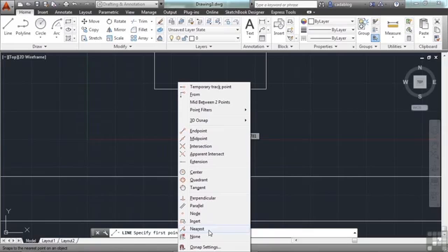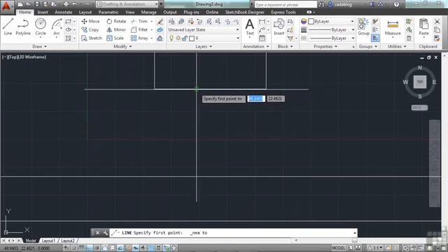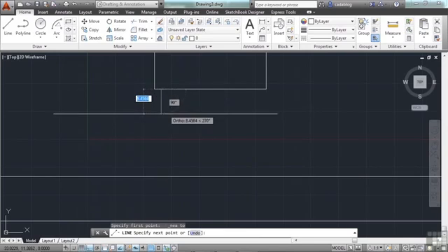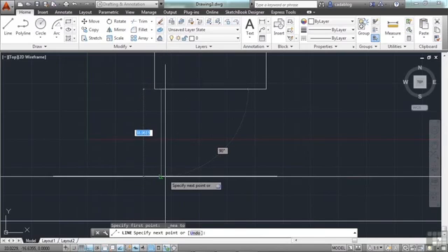It's the nearest OSnap. It's not the one nearest to where you're at. I actually mean literally the nearest OSnap. It's right here. Pick it. And now we're going to be able to start our line right on any of the places we pick from our house. Let's put the garage on the left side here. Left click, and then draw the line.